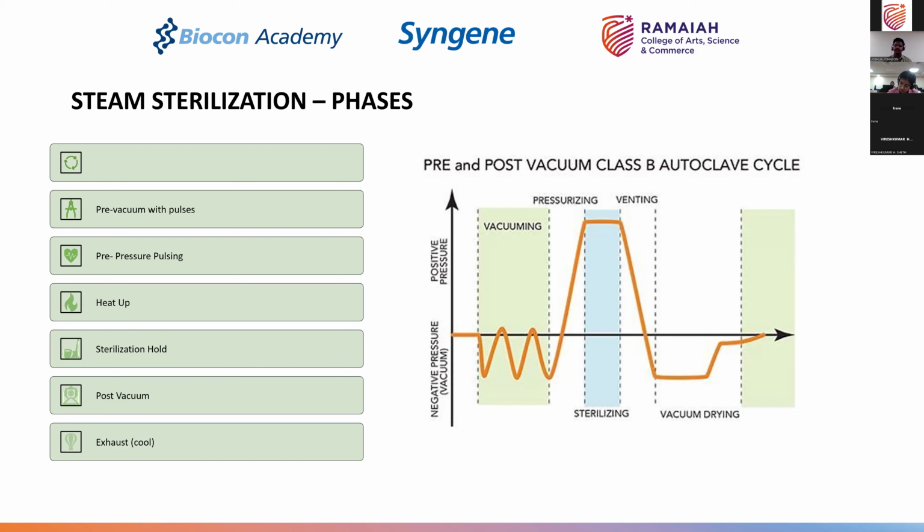And you do this multiple times. But it has been found that this technique works for, let's say, vertical autoclaves and smaller size autoclaves, because the quantum of air which is entrapped or present initially in the chamber is low. When you talk about large chambers, 2000 liters, 1500 liters, 1200 liters of air present in the chamber, if you use steam as a means of displacement, then that preconditioning will take a long time.